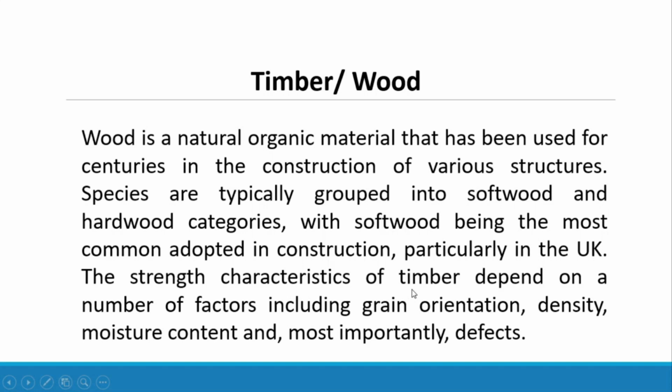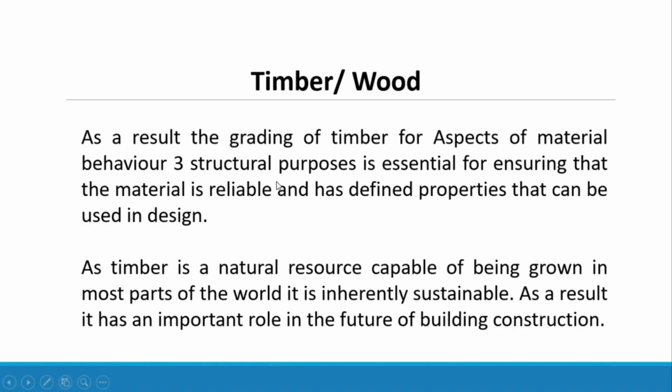The strength characteristics of timber depend on a number of factors including grain orientation, density, moisture content, and most importantly, defects. As a result, the grading of timber for structural purposes is essential for ensuring that the material is reliable and has defined properties that can be used in design.